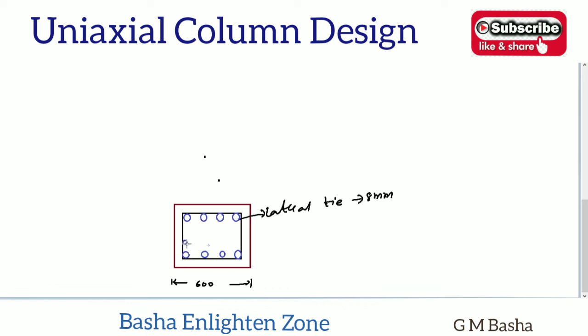So here also it will be 2. If according to the spacing it is not suitable, then provide 8 bars of 32 dia only. If it is suitable, you can provide like this. Check the specifications.